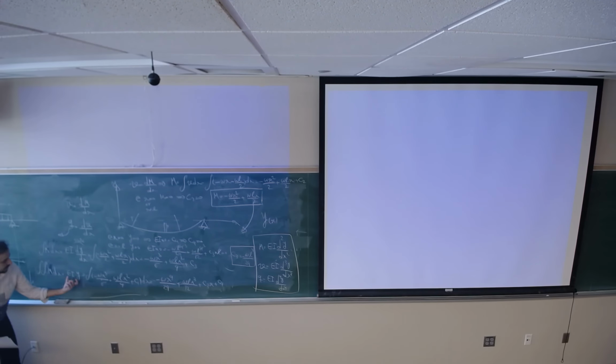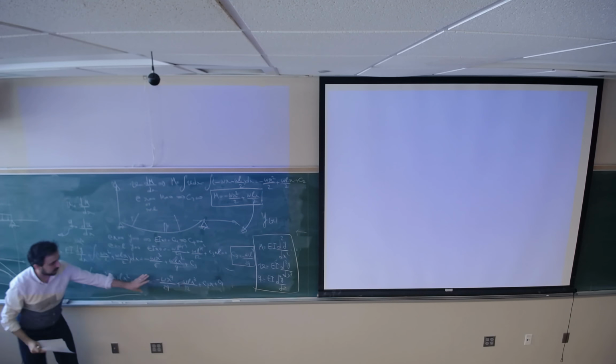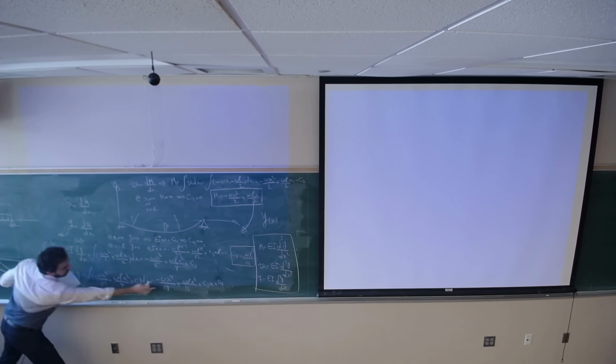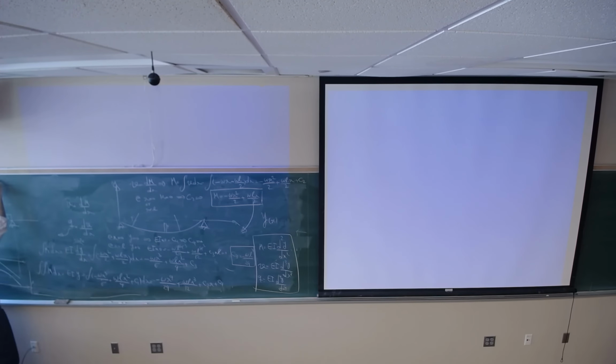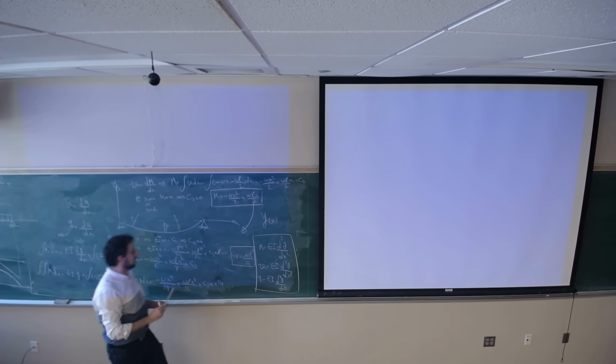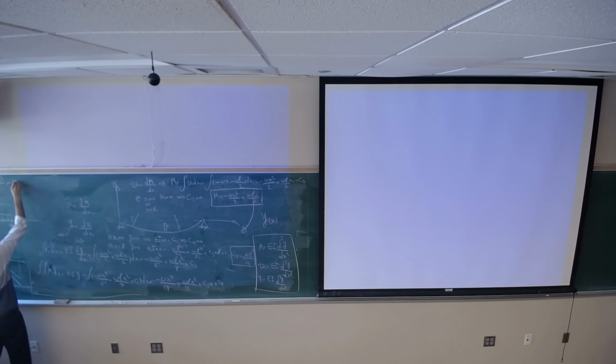Now I can write y as a function of x: y would be 1 over EI times negative w x^4 divided by 24 plus wL x^3 divided by 12 plus C3, which is negative wL^3 over 24, times x.